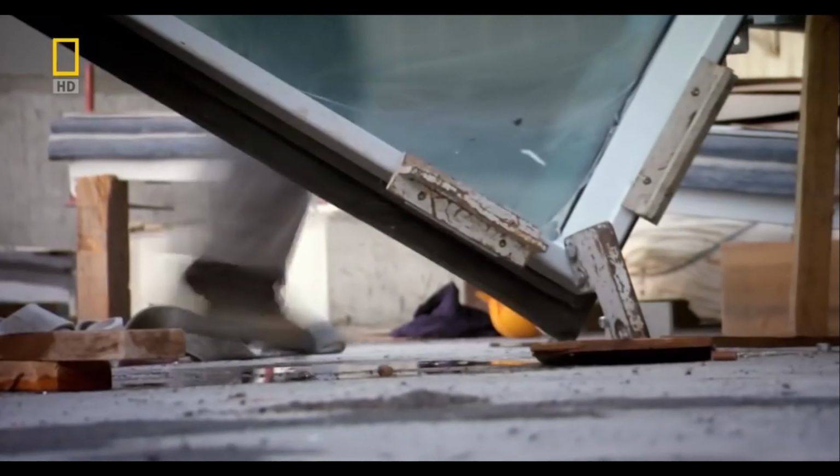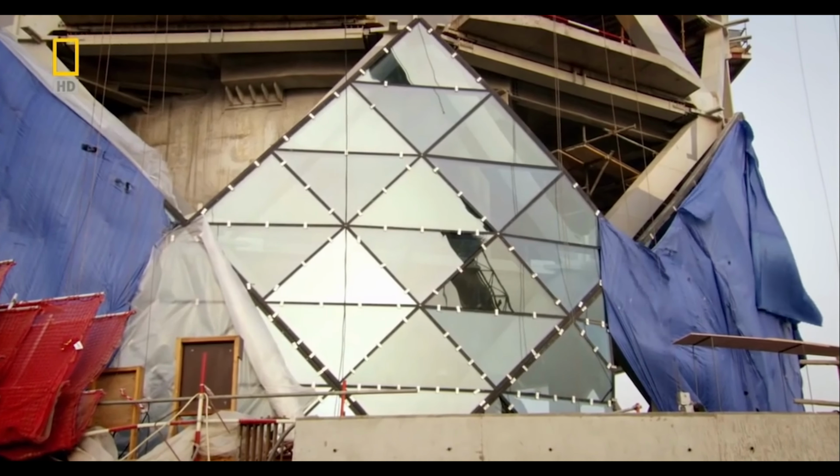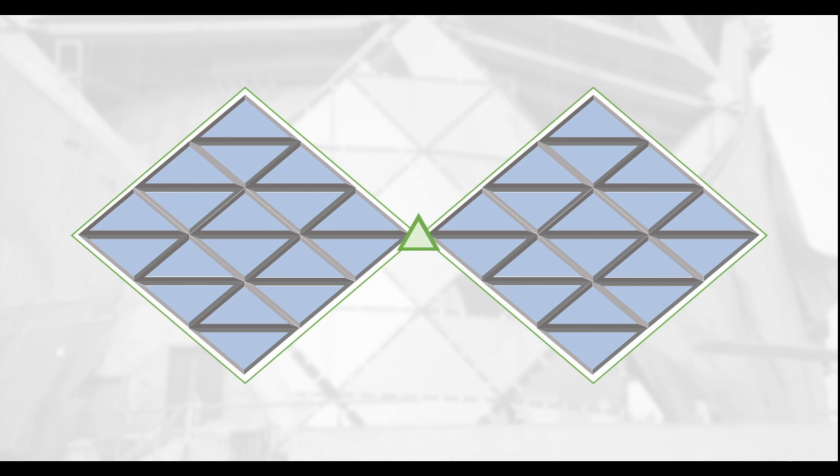With this difficult building, however, one problem is solved, and the other is just around the corner. How did they cope with this unpredictable extra movement? Normally, as a diamond-shaped unit has 4 vertex points, it would be reasonable to fix all 4 points. Each point meets with 3 other diamonds, and so in total, each node gets fastened 4 times, connected with each other. However, at Capital Gate, each large panel was fixed in just 2 places at each side.